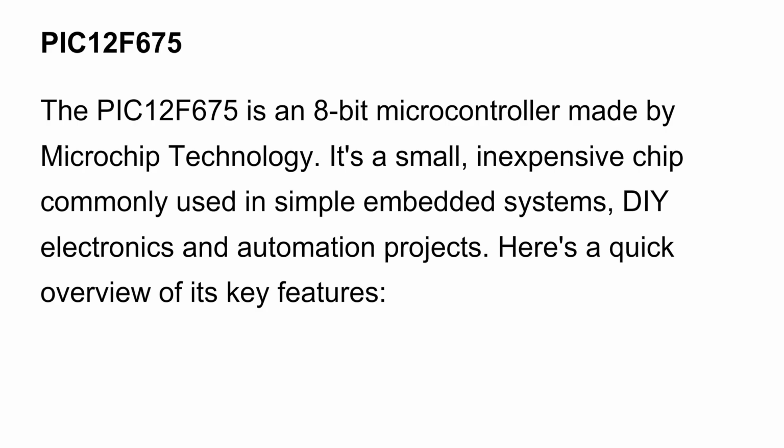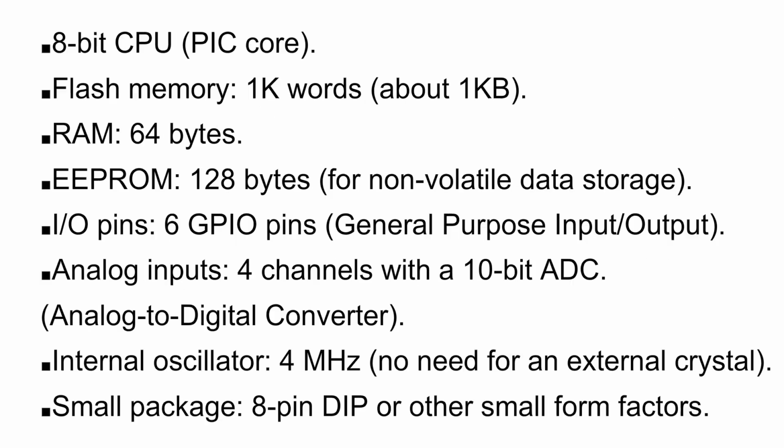It's a small, inexpensive chip commonly used in simple embedded systems, DIY electronics, and automation projects. Here's a quick overview of its key features. 8-bit CPU PIC core. Flash memory, 1K words, about 1 kilobyte. RAM, 64 bytes. EEPROM, 128 bytes for non-volatile data storage.